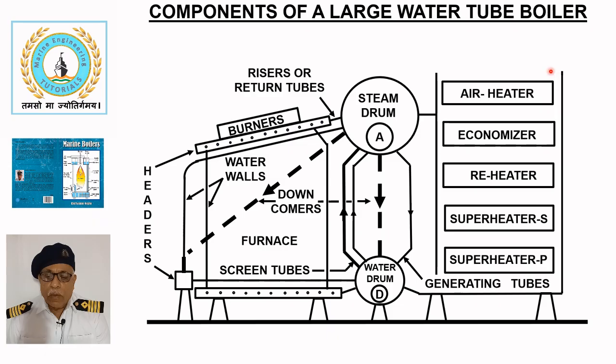Air heater. The air heater is typically a final heat recovery unit and preheats combustion air before it enters the furnace. Its location depends on the flue gas exit temperature. Excessive cooling of flue gases may cause sulfur dioxide condensation, leading to cold end corrosion. In some cases, bleed steam from the turbine may be used to warm the incoming combustion air.